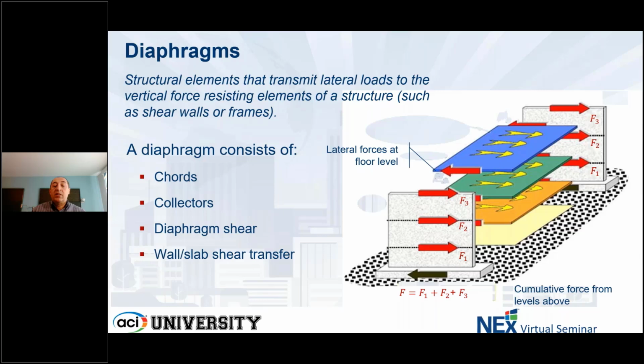Diaphragms are a little bit more complex, right? Because in reality, we don't have a simple, basic rectangular slab, as I'm going to show in the next few slides, a simplified example. We have an odd shape for these diaphragms, and we have shear walls that are not uniformly distributed, and we have openings. So detailed analysis with finite element-based software is important so that you can determine exactly the shear demands, the forces, the chord collectors, the drag forces going on within each floor that need to be strengthened with FRP.